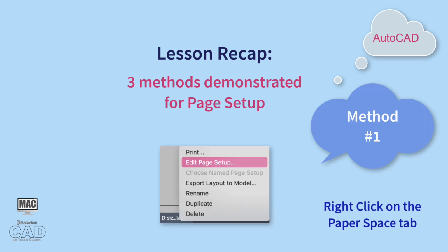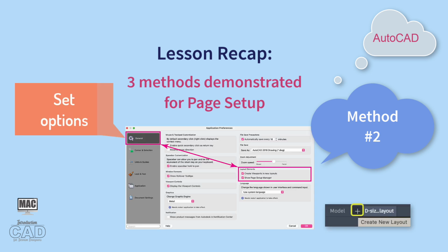Number 1. Right-click on a Paper Space tab and choose Edit Page Setup. Number 2. In the Options settings of the program, assign the Page Setup Manager to automatically populate each new sheet created through the plus sign, located in the lower left-hand corner of the screen.